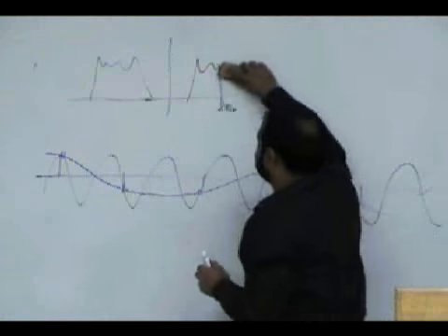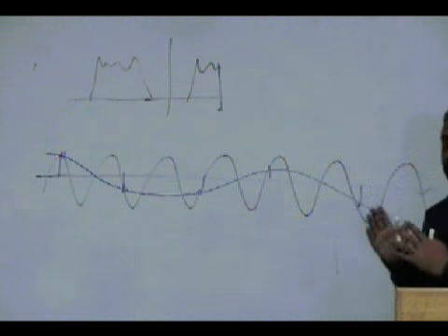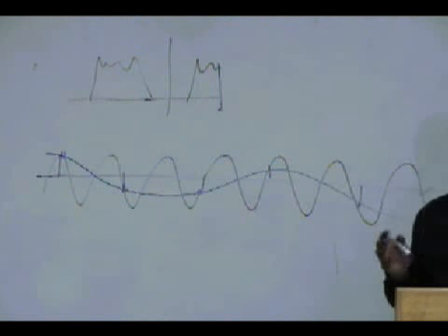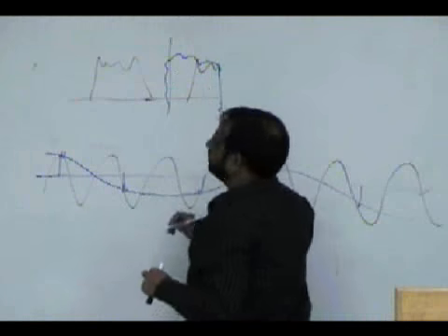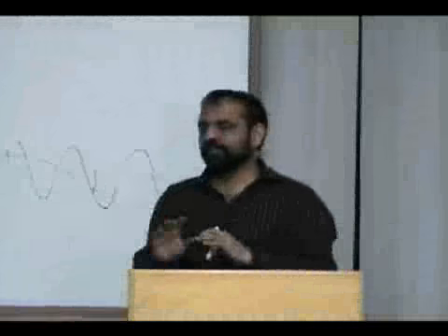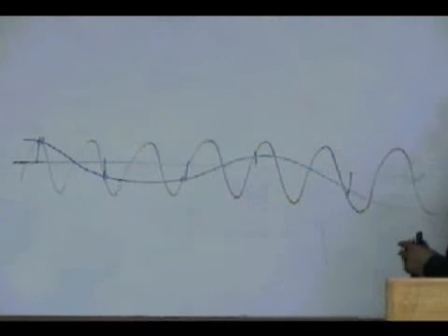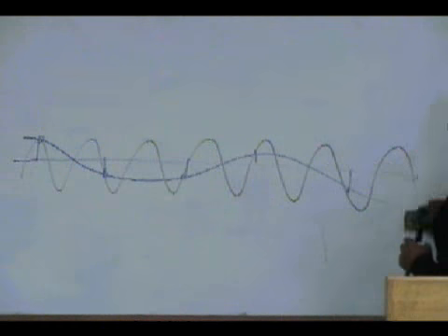Once you again take the spectrum, this is, let's say, the spectrum of a continuous time signal, and then you inappropriately discretize, see the spectrum. You may find the spectrum just doing this everywhere, and not what you are seeing on the analog spectrum. This is the digital spectrum, which may be totally different from the analog spectrum, and this is the reason that if you don't sample fast enough, you are generating a frequency. So though you are losing the high frequency, you are generating a frequency which will come back and corrupt the original frequency in the signal. I think this is